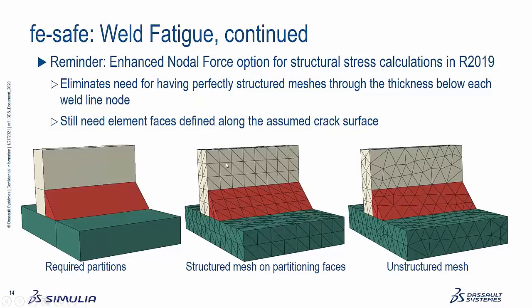We changed to what we call an enhanced nodal force method, where now you can use far less structured grids, but you do still have to partition along the crack plane. So if you want to have the toe failure through the plates here and here, you still need to partition that geometry so that we end up with element faces on that crack face.